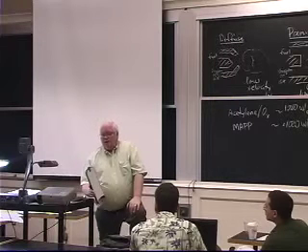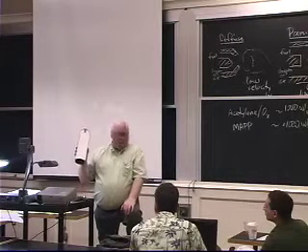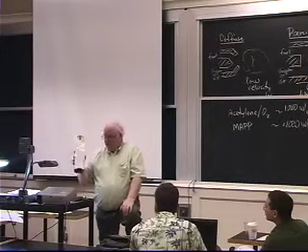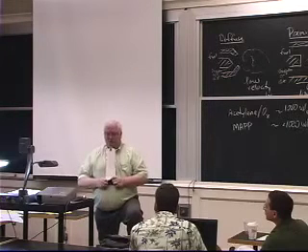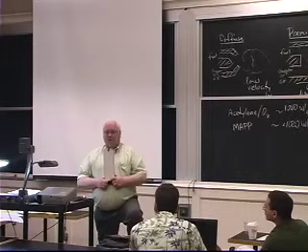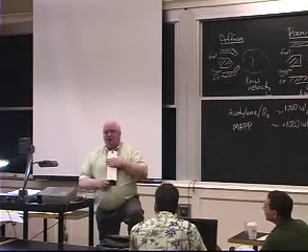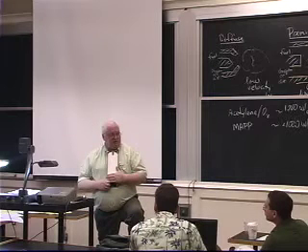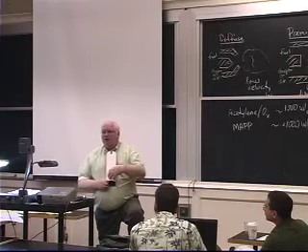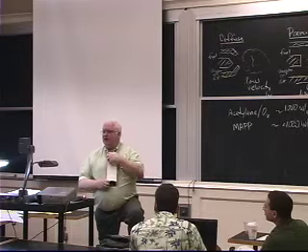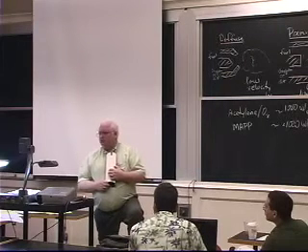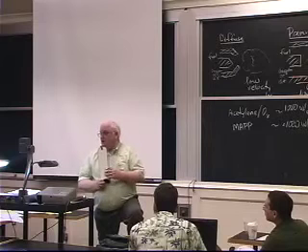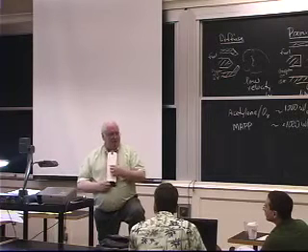Because to transport acetylene, you have to do it in a cylinder like this, and I'll pass this around next time. This is in the class right now. But this is a cross-section of a B cylinder for acetylene. I'll tell you what B means in a second. But the acetylene cylinders, tanks that you see, are actually filled with a calcium silicate ceramic that's 92% porous. It's only 8% solid here. It looks solid, but it's very porous.